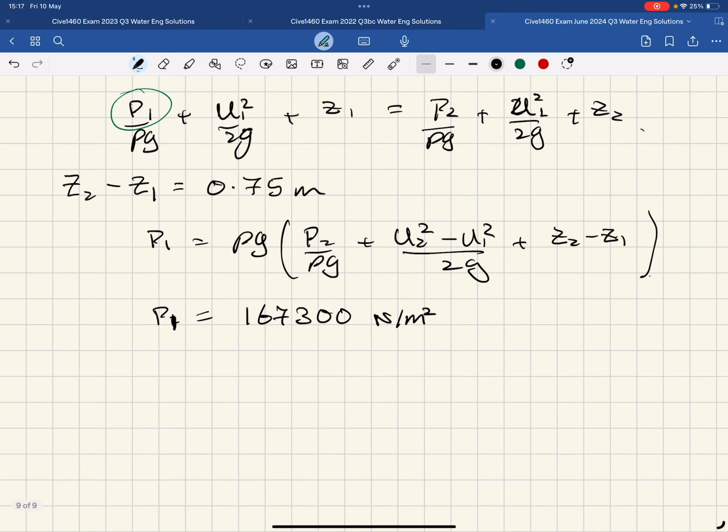Right, we need to do the pressure force calculations in the x and y directions now. Fpx is equal to P1 A1 cos 0 minus P2 A2 cos theta. We put the numbers in there, and we calculate this would be 3296 newtons.